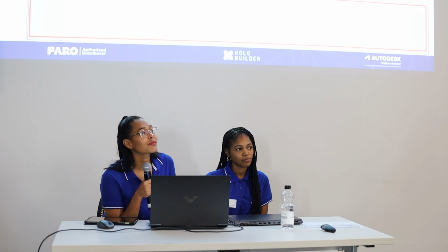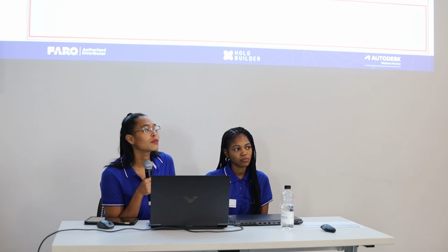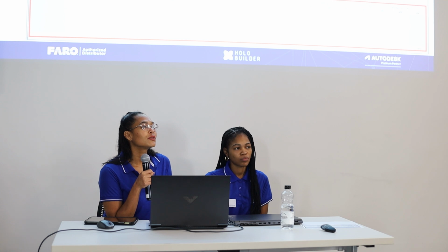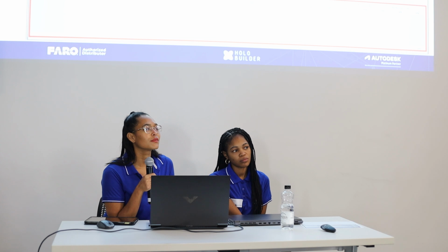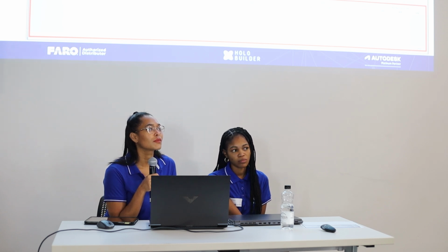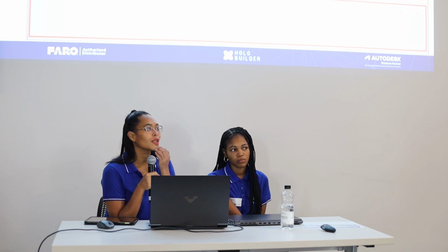I have one. The information on the clash detection, when it's been identified in Navisworks, how does that get pulled through into your software like Revit? Is it with a visual representation? Like for instance, if you go to ACC where you do clash detection through ACC, you log a design issue with a node on your project model, where it gives you a call out with the information related to that clash. How does that then translate back into Revit? How would you identify it without going back to Navisworks? Or do you need to then export a schedule of clashes to your design team to have them then identify it manually throughout the project?